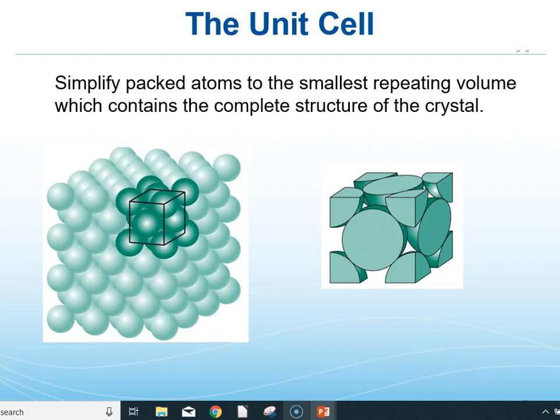As you can see, we're whacking them. The face atoms, only half belong to that unit cell, and on the corners, only like an eighth. And that's really important when we start talking about atomic packing fraction, density, linear and planar packing fractions. It's very important to know how many atoms belong to a given crystal, because that's how we're going to add those things up very quantitatively. And then those properties will in turn tell us quite a bit about the materials we make out of these crystals. Believe it or not, these are really important for a lot of the material properties we design to.